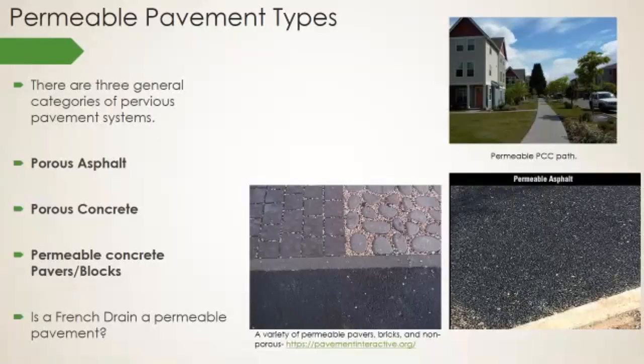And as we've mentioned with porous asphalt, we have porous concrete. And porous concrete is pretty similar. It's much like the asphalt. Again, it has those fines removed to create those air spaces, developed in the 70s. And this one is more for driveways, even more limited traffic. Maybe you might find it on the side of a street where only cars are parking, so the parking lane or bike lane, a mixture of those two, definitely used for walkways, driveways, and footpaths. So things of that nature, possibly even parking lots, but probably not for more steady traffic that would be like a through street.